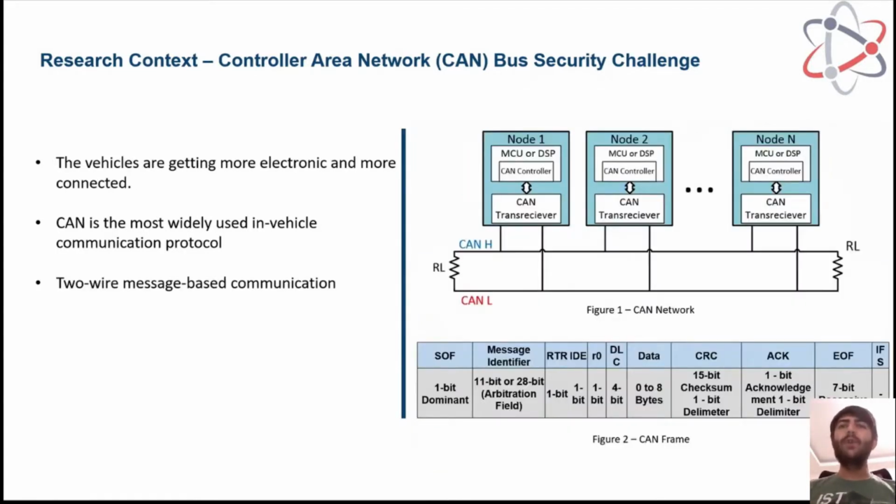As you can see in figure 1, CAN bus is represented as two wires, CAN high and CAN low. Each node is attached to this network, therefore it is easy to maintain. The CAN bus is a message-based communication protocol. Each CAN message has a priority bit, which is in the message identifier field, providing priority access to the CAN network. The CAN protocol is also relatively cheap compared to other protocols. Therefore, it is mainly used in the automotive industry.